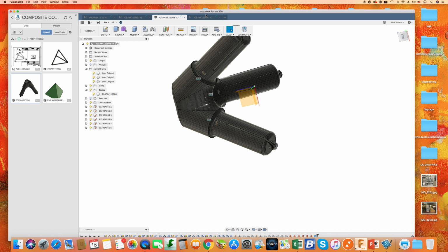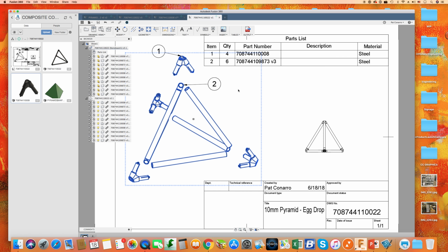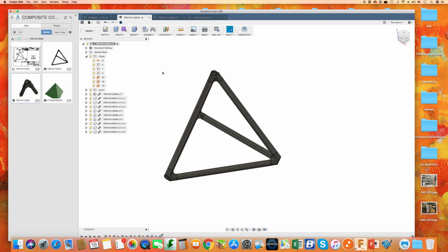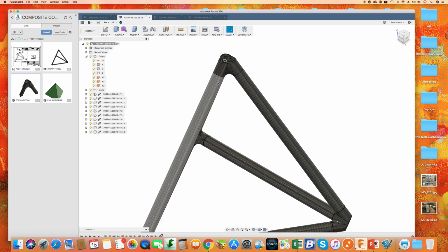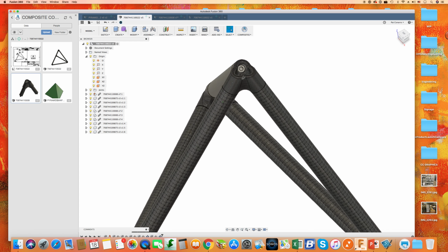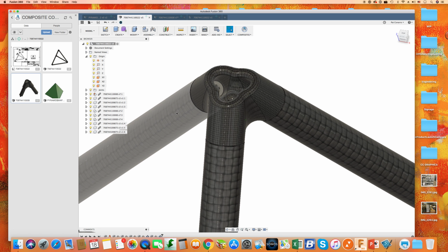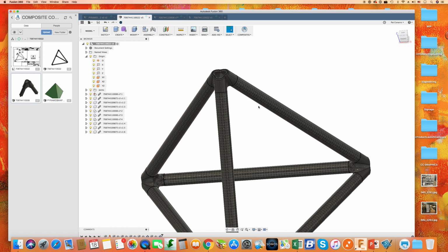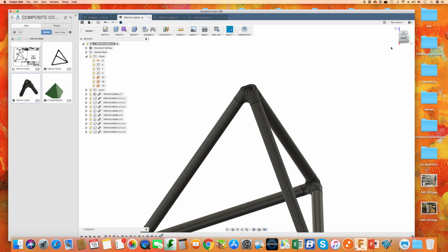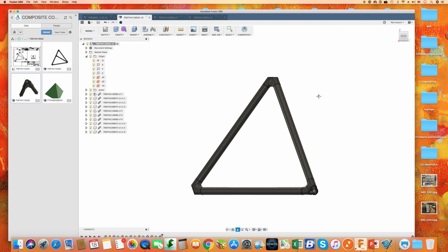And so when we look at the main assembly, we go back to this assembly right here. The idea is that we 3D print this and then we put a metal screw in here from McMaster-Carr and we open it up inside. There's no draft. It's not like a molded part. We're 3D printing everything. And then we design it and then you make a short drawing.